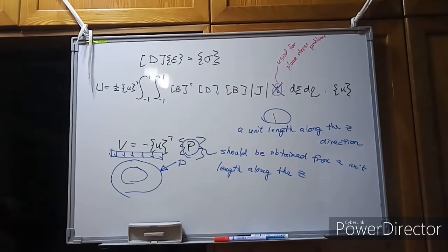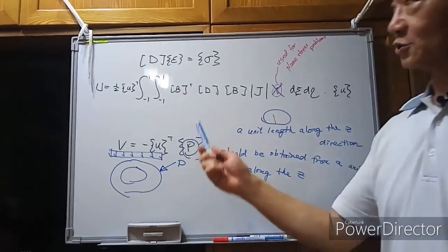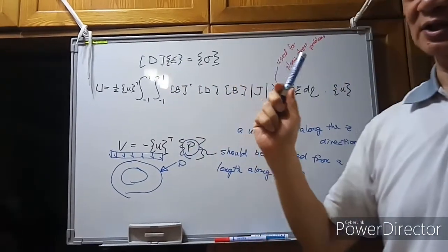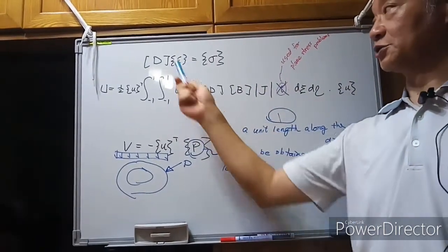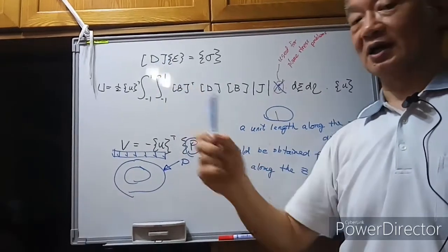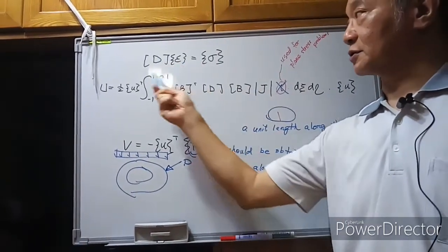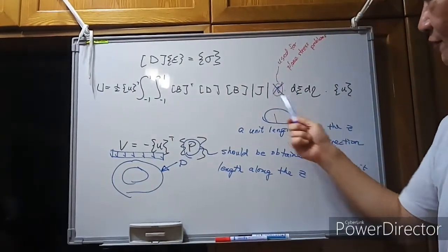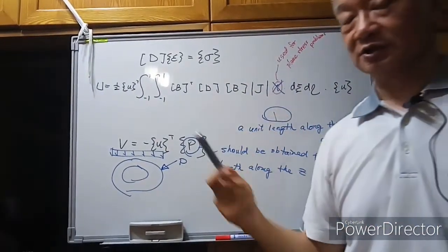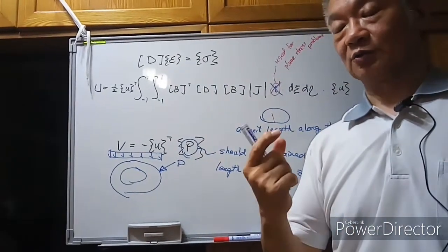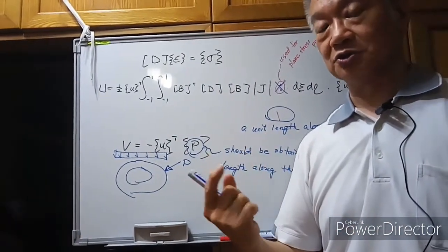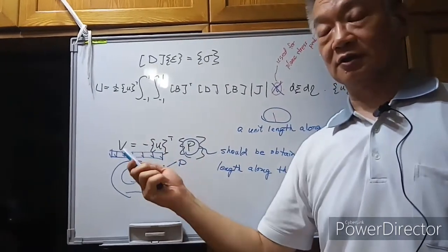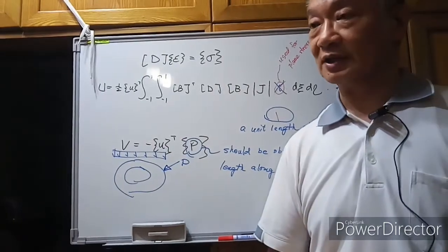Okay, so actually, if you compare the plane stress problem and the plane strain problem, there are only 2 differences so far. The first difference is the D matrix. The second difference is the thickness we need to calculate. No matter when we calculate the strain energy U or the V, the potential energy due to the applied loadings.